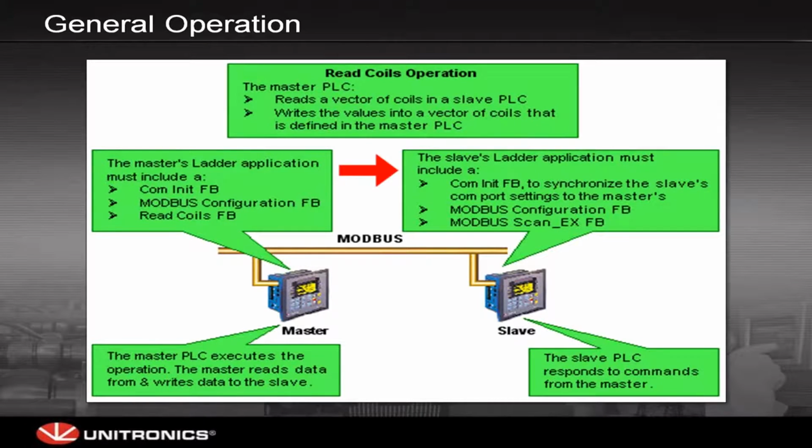And today we're going to be looking at MODBUS RTU, which is MODBUS serial. We also support MODBUS TCP, which is over the Ethernet layer. We're not going to be looking at that so much today. We already covered that in an earlier webinar on Ethernet. So if you are curious about MODBUS IP over Ethernet, you can take a look at the previous webinar that we have for that. But today we're going to be focusing on MODBUS RTU, MODBUS serial, and we support that over the RS-232 or also RS-485 network.